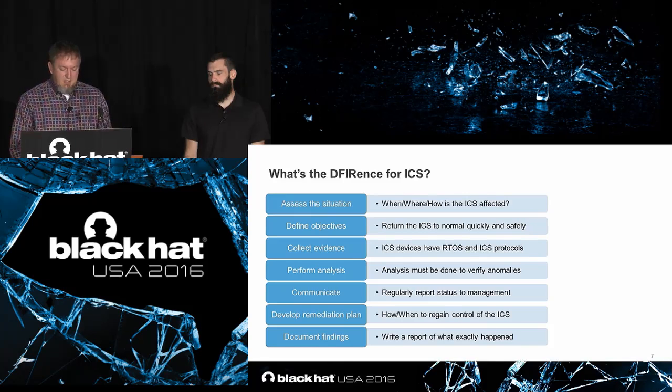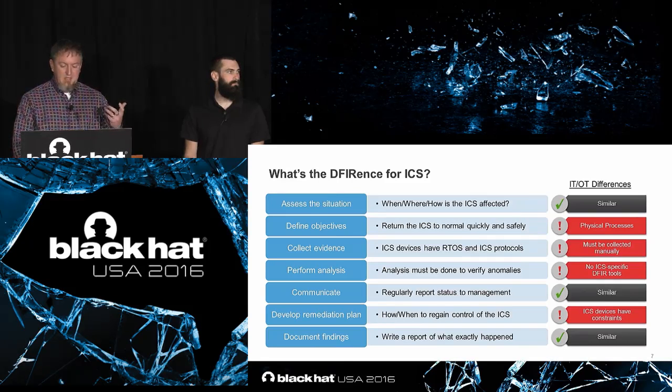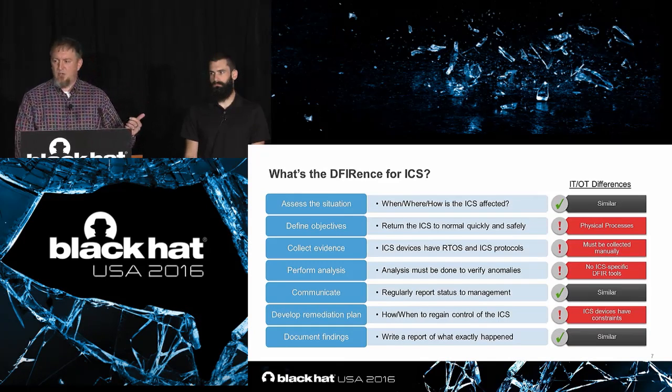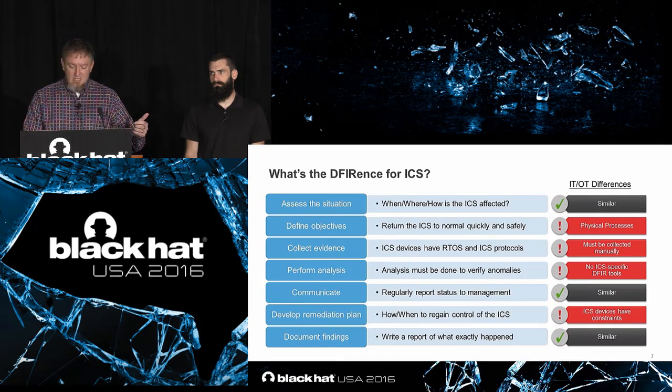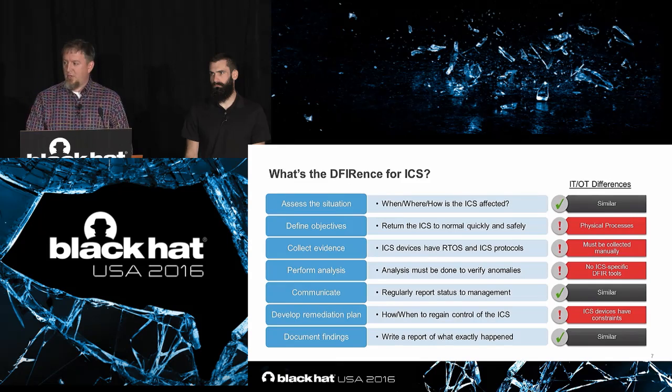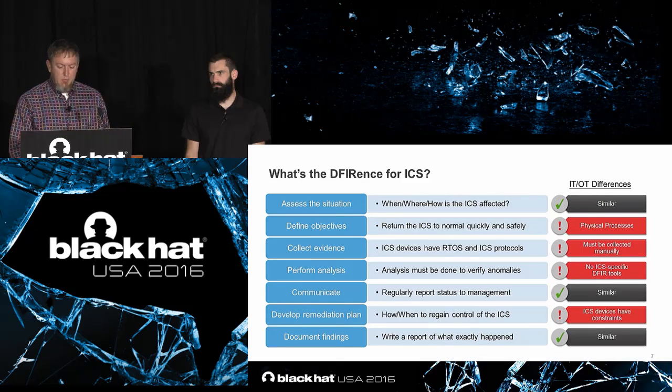So how is ICS affected? You know, assess the situation, that's the same. And we have some other things that are the same, like communicating to management what's going on, and documenting the findings are similar. But, you know, the physical processes are different in IT devices compared to control system devices. We want to make sure the control system is returned back to a safe state. And the ICS devices have real-time operating systems and control system protocols that are not IT-centric. So we have to collect these manually. And the analysis has to be done by hand. There's no tools.